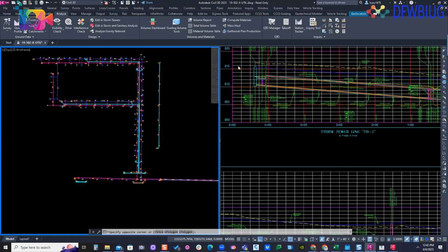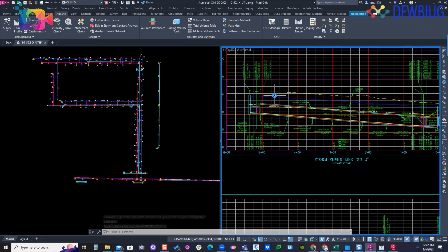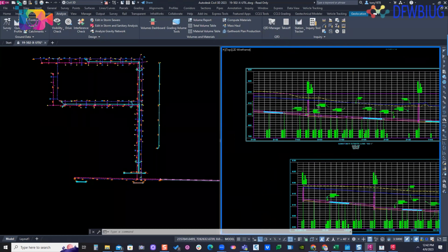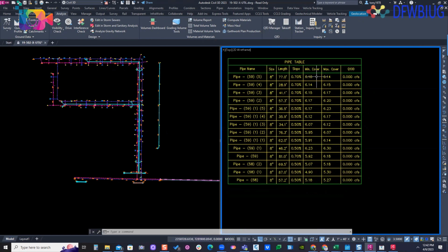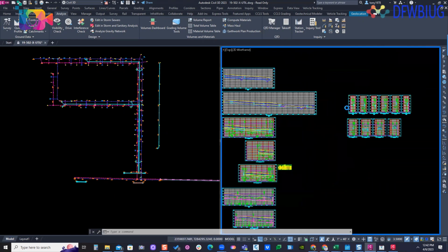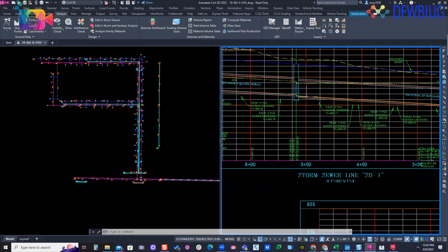But this is something that most engineers are very picky about, who's doing hydraulics. So I've been doing it for a long time. Most companies I worked for when I was a CAD manager, I was doing the design, I was doing the hydraulics, I was doing the detention pond, I was sizing the storm pipes. And then the engineer would just double check. In here, I usually create these tables to double check my work, pipe coverages and cuts and stuff like that. So laterals over here, double checking lateral hydraulics. But yeah.